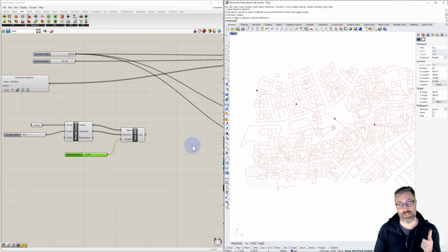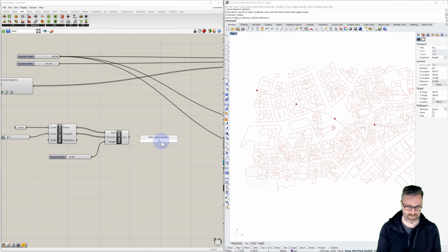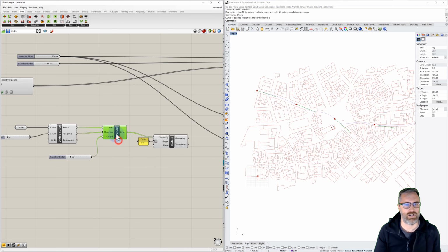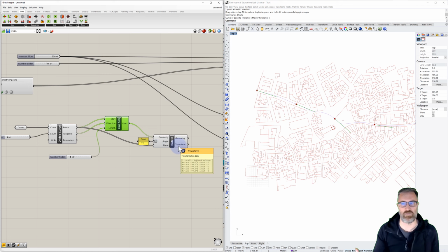And so with that, like we did in the last tutorial, let's rotate a line 90 degrees. And as we rotate this, the geometry that we're going to rotate is our line. The angle we want to set to degrees. We set a very small panel, set to 90. And our plane will be equal to, let's cheat for now and set our plane equal to our point, which again defaults to XY. We're working in the plan, so XY is fine. So now we see we've got two perpendicular lines at that point.